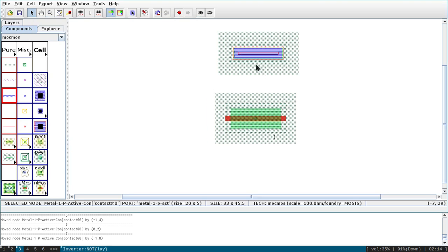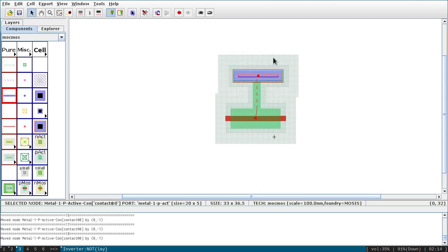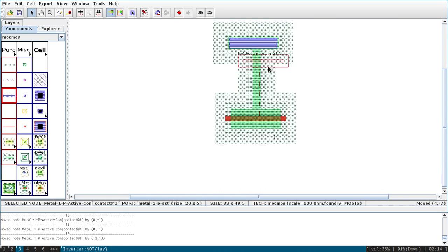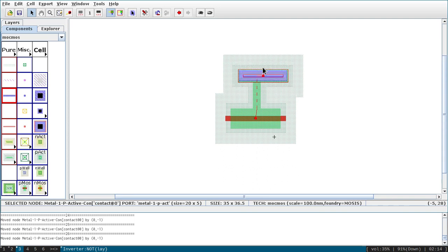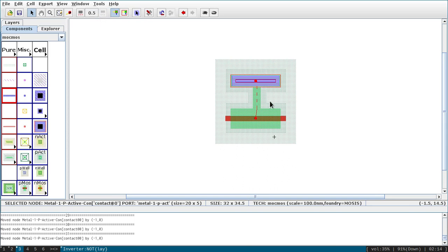Okay. And what you have to do is select the MOSFET, click on the source terminal, and right click on the contact, so that a contact is created between these two. Now you take it near, you can either use the mouse to move it, or you can simply use the arrow keys. I feel arrow keys are more convenient, so you can easily control it.